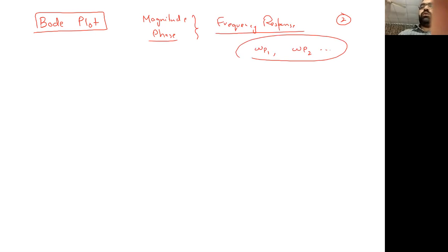One thing we just got to know, if we have seen this common source configuration, the pole was linked to this capacitance and this impedance here. So this pole has some relation with this capacitance and resistance. And what is that relation? It's inversely proportional to the product of impedance. I'm just writing a resistance and a capacitance.